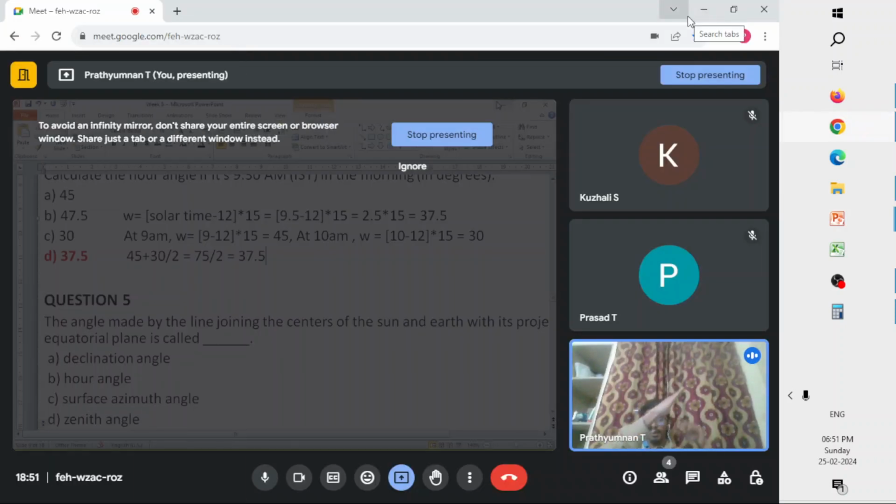So this is your flat plate collector, but in the case of zenith angle, you assume that your solar collector system can be anything, not necessarily a flat plate collector, it can even be any kind of concentrating solar system. If you take that system to be on the horizontal surface, with this normal, and let's assume that the sun is in that direction, that is the beam's direction, then the angle between the beam's direction and the direction normal to this collector system on a horizontal surface is called your zenith angle.